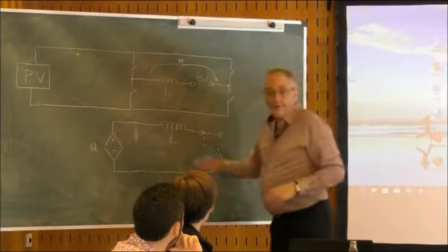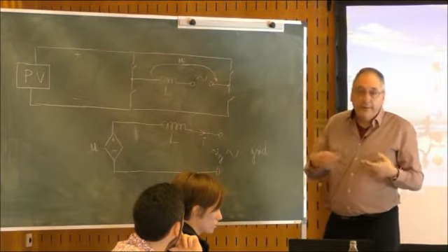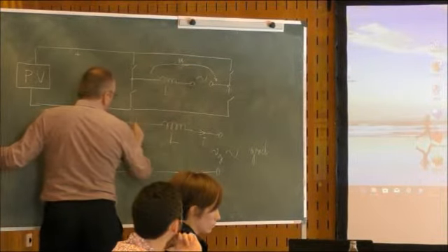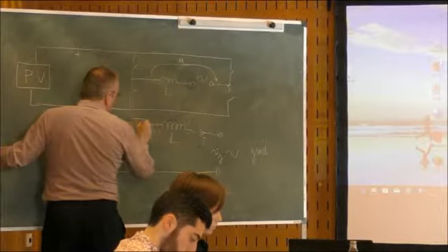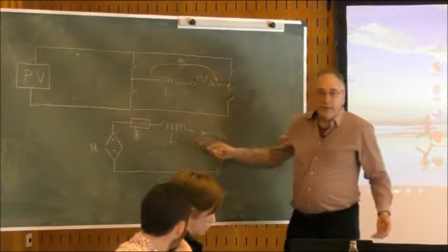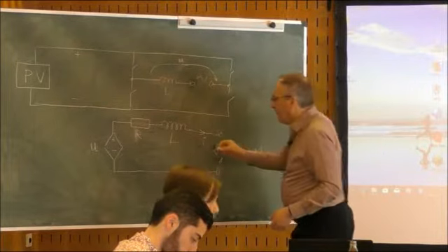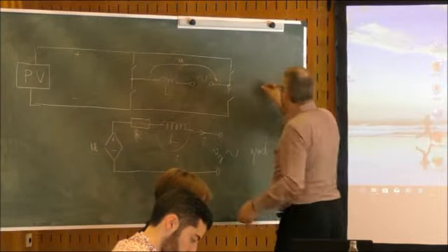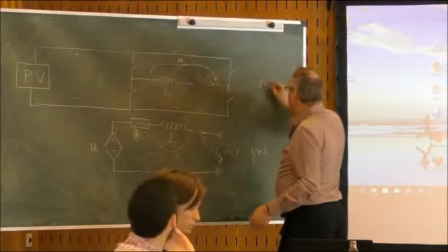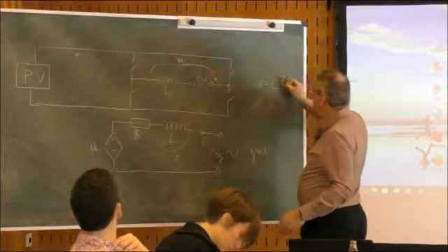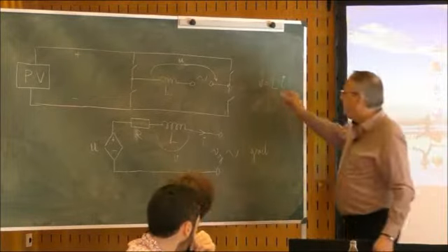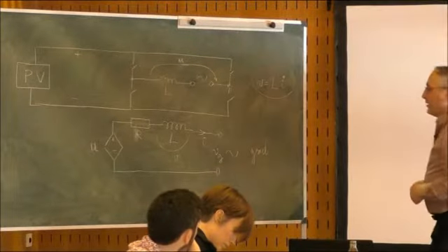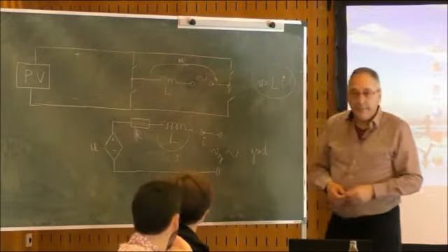And when you make a real inductor, this inductor will also have a resistance. So we have to represent the inductor as being a resistor in series with an ideal inductor. The ideal inductor is of course represented by, let's call the voltage across it V, so V is equal to L times I dot, I dot meaning the derivative of the current. So this is the equation of the inductor, and I want now to see what is actually my system.